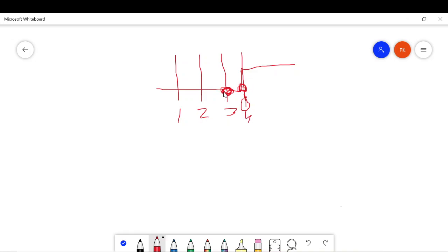So using this previous value and the current value, I can determine whether there is a transition from 0 to 1 or not. Whenever I see a transition from 0 to 1, that is an indication that a new data set has been written onto slave register 0 and inform_valid has gone from 0 to 1. So whenever there is a transition from 0 to 1, I get an indication that a new data value is written on slave register 0, and I need to perform the calculation on that.